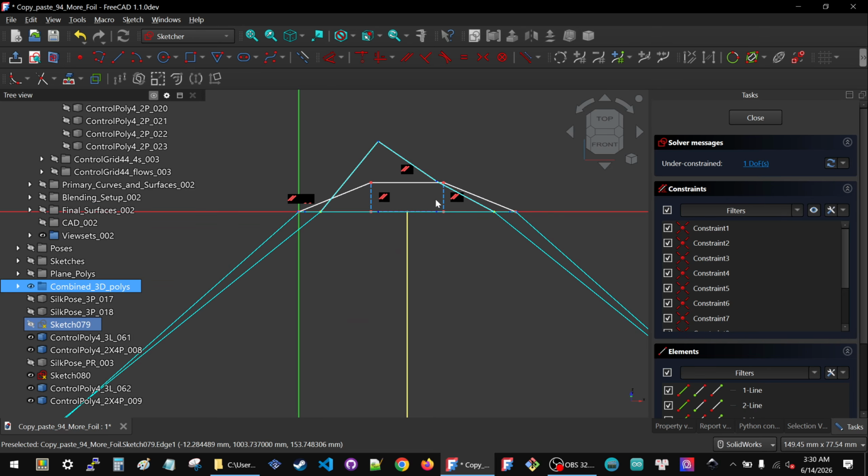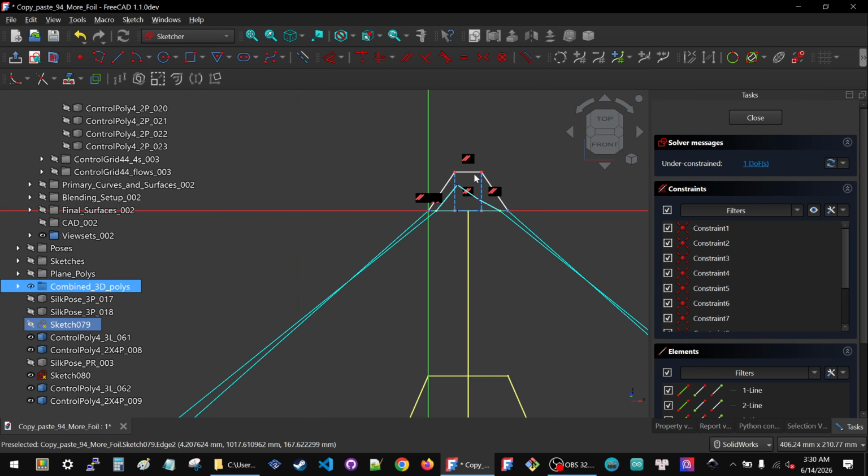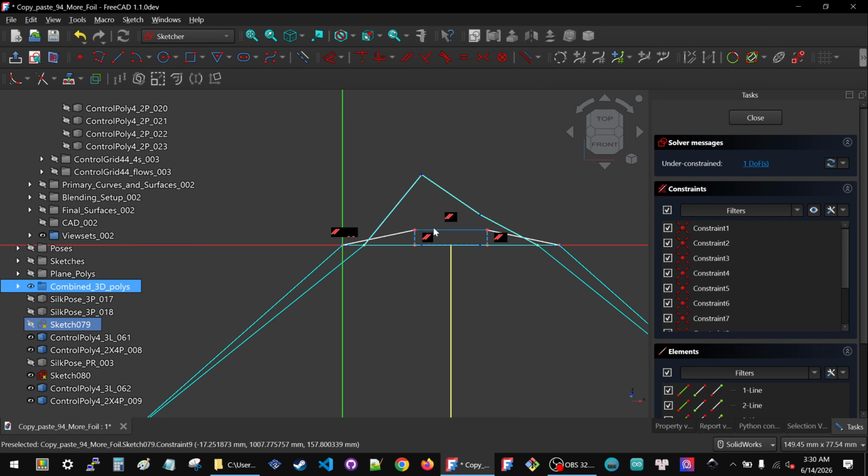And what this means is that this polygon, this leg here, cannot be aligned to this object. And it shouldn't be above either, because if it goes above, it's going to fold the surface. This is one face, so it should form some kind of simple quadrilateral with distinct outer angles. See, this is an outer angle. This is an inner angle. Inner angles fold over. We don't want that.